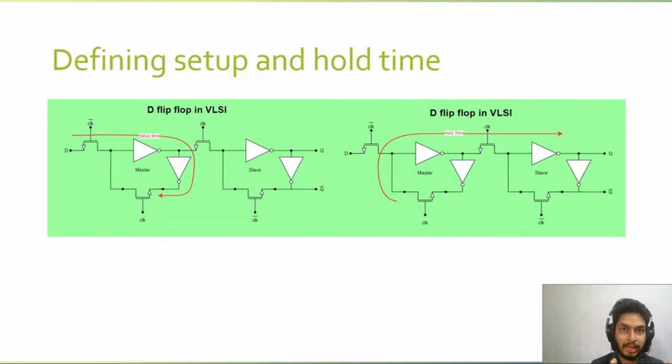But I want you to think one thing, that setup and hold time and setup and hold checks are two different things. They are not the same. Setup and hold times are the requirements of the design, right? They are fixed. If we have a standard cell of a flip-flop, for that standard cell, the setup time is fixed. And that is the requirement. And setup and hold checks are the checks to ensure that these setup and hold times are really met. Okay, so there are two different things, right?